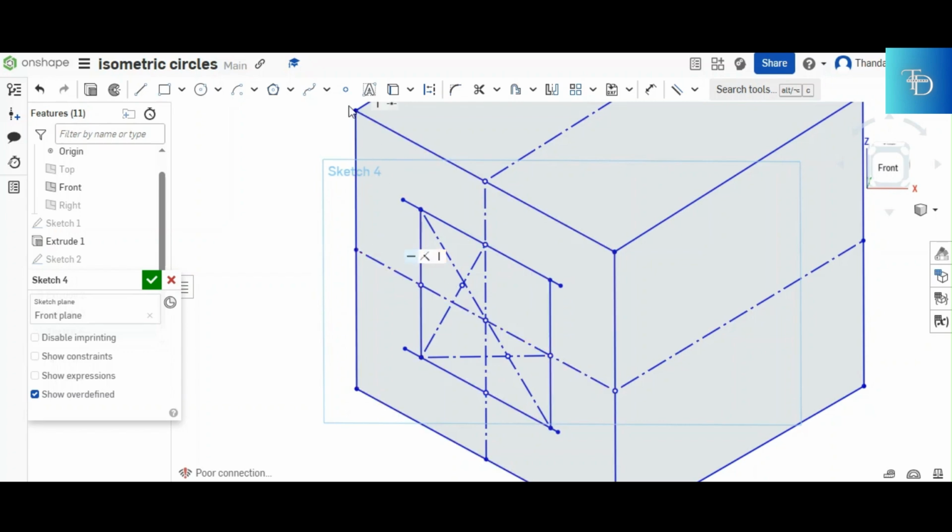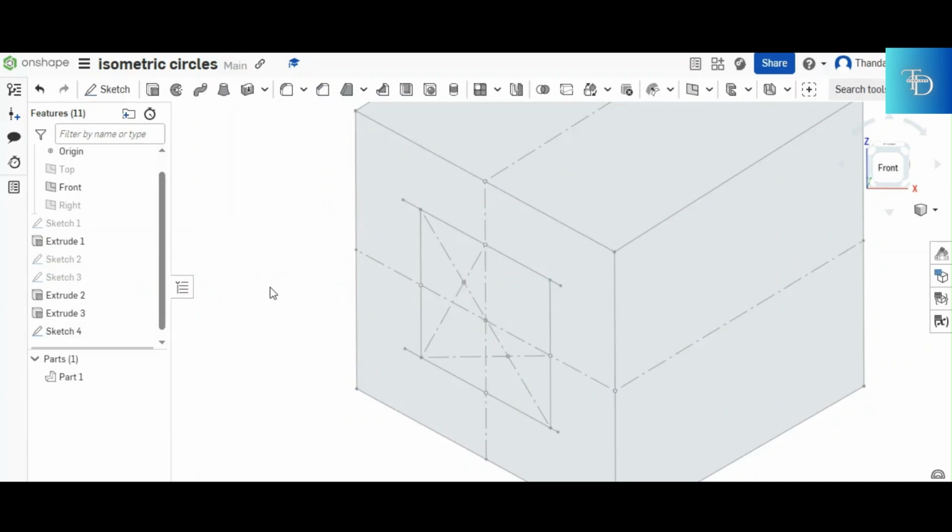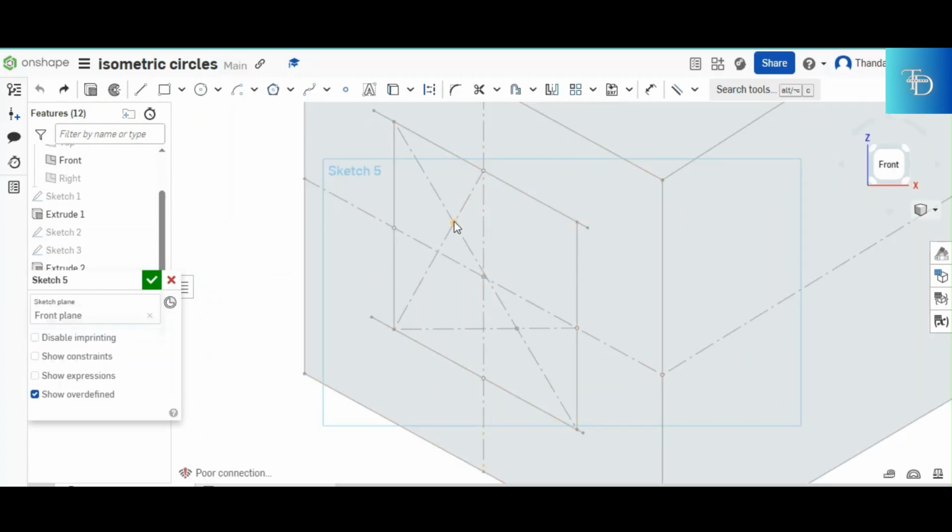4 center method. So now remember that everything you did here, you did it in faint lines. Now the only thing that is left for you is to take your compass and create the 4 curves of your circle using those 4 center lines that you've marked out. Place your compass there. You complete the first curve.